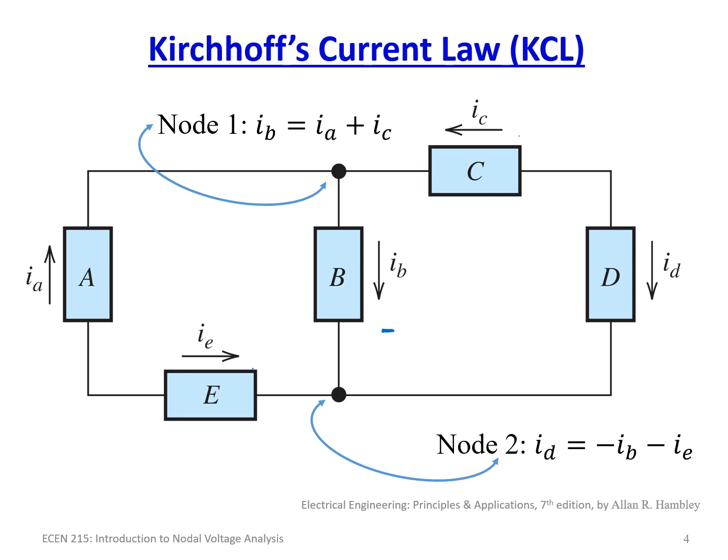That's really common. Actually, it's called a strain gauge interface, where as the pressure in a vessel increases and you've got a sensor that's exposed to that pressure, its resistance will increase and decrease depending on the pressure. So if the pressure is at, say, 0 psig, it could be 1,000 ohms. But as the pressure increases, it has a linear relationship, so that if it goes to 1,000 psi, instead of 1,000 ohms, it's now 10,000 ohms.